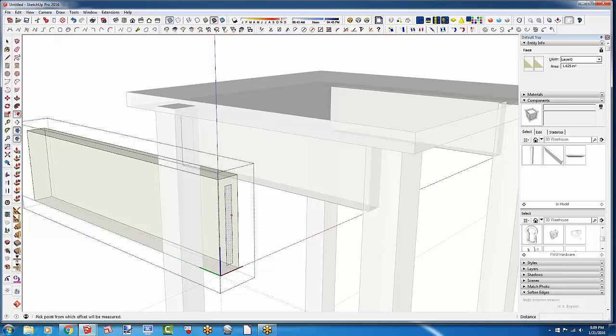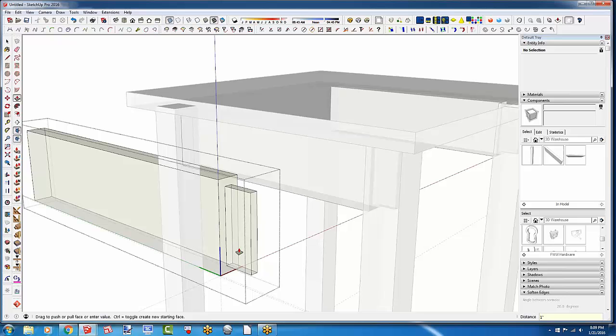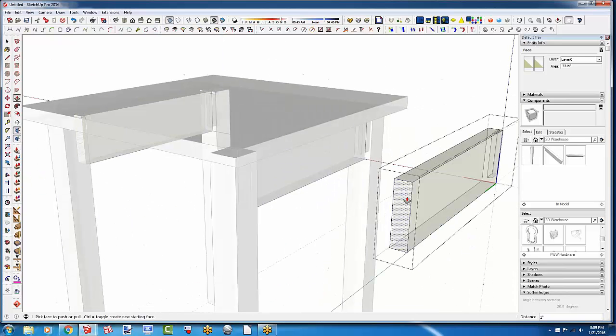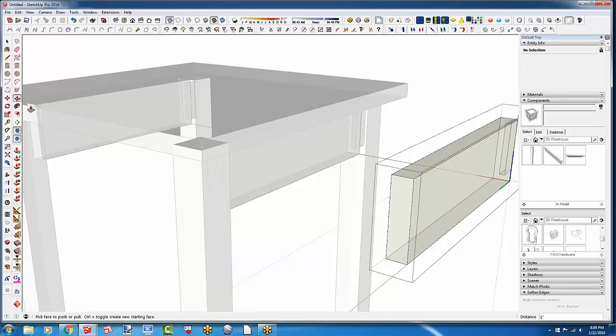I can go in 1/4 of an inch, so I just put a line in all the way around at 1/4 of an inch from the outside edges. I'll put it, well, that's a long tenon, but that's okay for this. And then I'll repeat the process. So I'm going to use offset again, and this time I can double click, and then, come on, you went backwards. It normally comes out the other way. There.